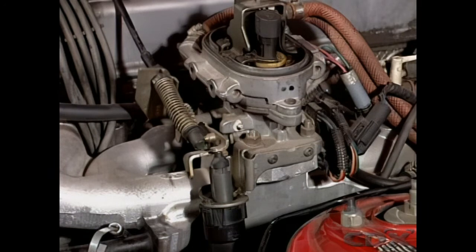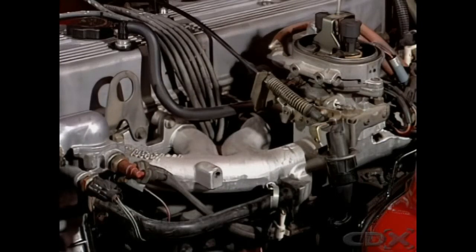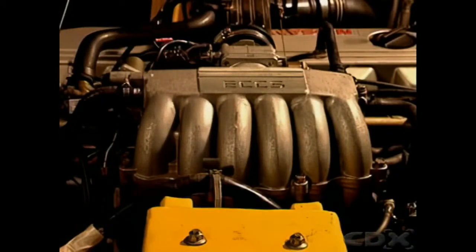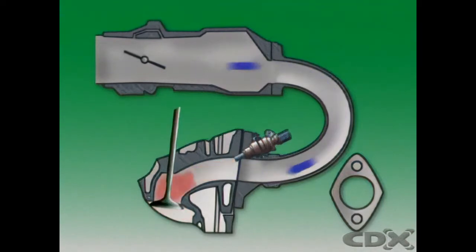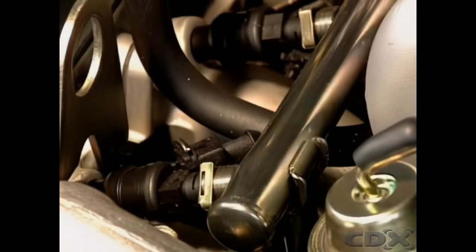Electronic fuel-injected engines with throttle body injection also have intake manifolds that carry air-fuel mixture. With multi-point injection, the intake manifolds carry air only, and the cross-sectional area of the tubes can be larger. More air can flow and the engine can produce more power. Fuel is injected into the intake ports of the cylinder head.